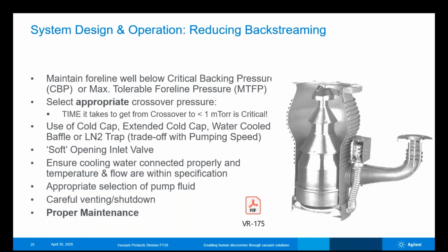Selecting an appropriate crossover pressure is much more complex and is also much more unique to each individual system. And what we'll find is that we want to be able to engage our high vacuum pumping system, our diffusion pump, as early as possible, but we need to be aware of how long it's going to take for it to be operating well within its comfort zone or its sweet spot. Wherever we're operating that pump above an inlet pressure that it's comfortable with, we're going to have that potential for oil mist going back. We're going to start to see a breakdown of those jet cones, of mist coming out from the different stages.